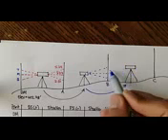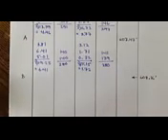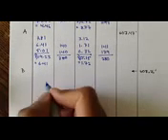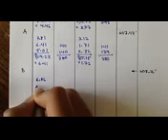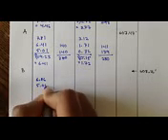So you take the instrument from here, you move it here, you take the backsight, and you take the foresight. And the backsight readings, your top, middle, and bottom, you get 6.86, 5.04, 3.20. Remember, this is for the backsight.